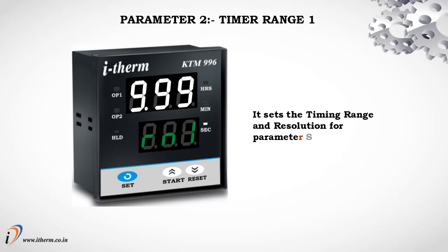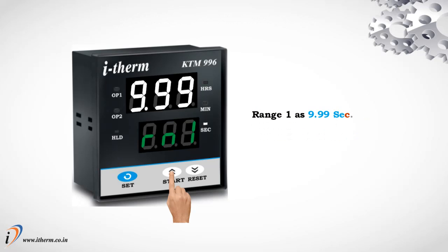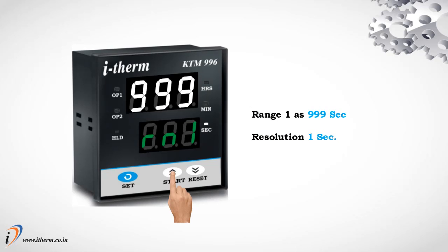Parameter 2, Timer range 1. It sets the timing range and resolution for parameter set time 1. Range 1 as 9.99 seconds. Resolution 0.01 seconds. Range 1 as 99.9 seconds. Resolution 0.1 seconds. Range 1 as 999 seconds. Resolution 1 second. Range 1 as 9 minute 59 seconds.